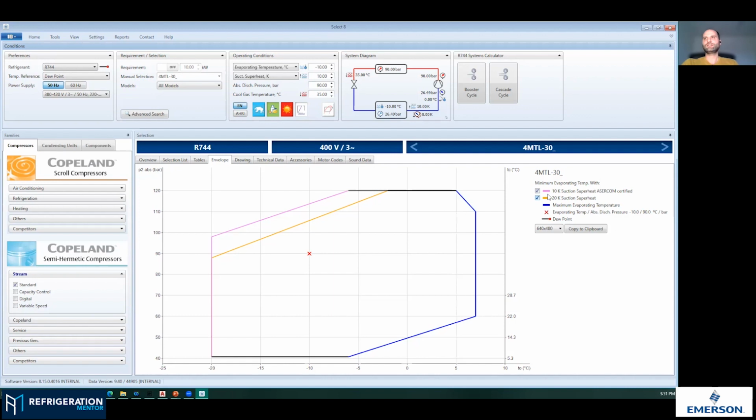I can, sure. What is shown here in the top left are two typical suction conditions in terms of superheat. The minimum recommended superheat for transcritical operation is 10K, or 18 Fahrenheit, and that is the bigger operating envelope here. So if you keep this recommended superheat, you can go up to -20 on the suction and 98, I can check it later on exactly, but it's something like 98 bar on discharge.